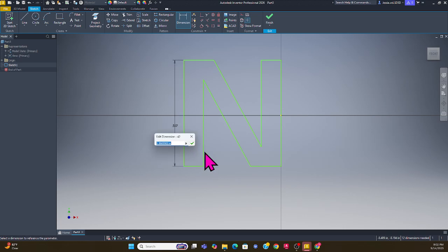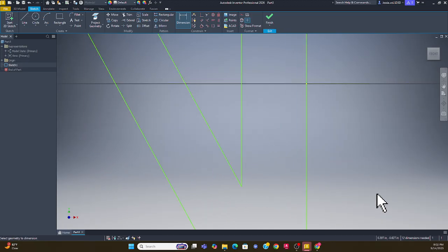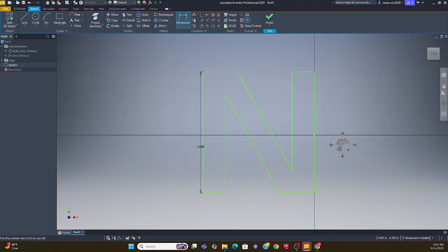In my previous video, I showed you guys how to change the units here. So this, I'm going to change to 2 units. And then I'll double click using my roller, and then it just zooms back out for me. All right, what's next? I would like to use the same dimension over here, so it's already there because they match when I drew it. This one, let's make it 0.6.